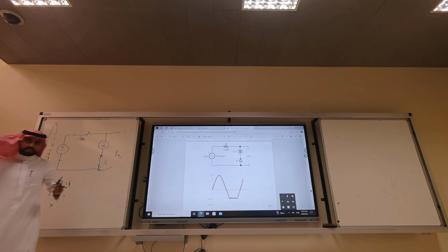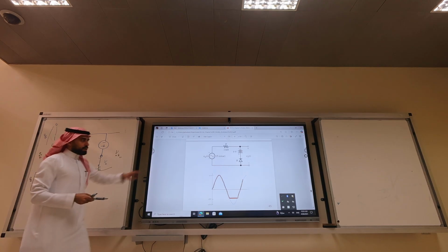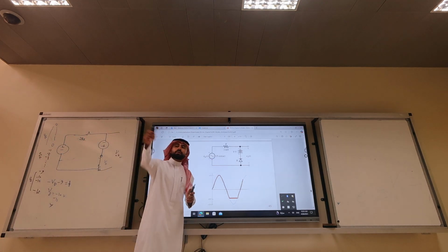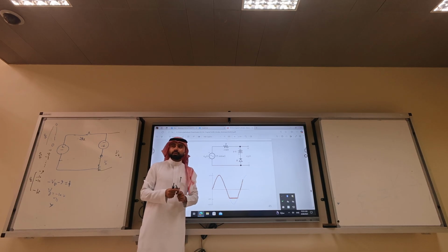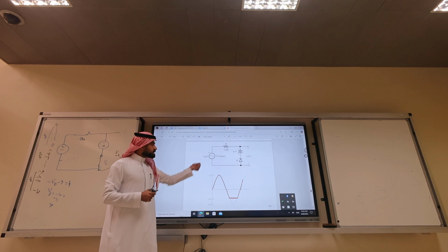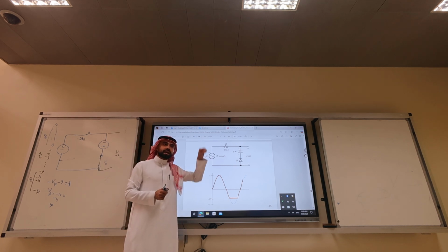That's how to analyze these circuits. The clipper circuit. Understand this example? We didn't do assumptions. Why? Because it's variable. So the best way to analyze circuits with AC sources and a diode is to study it case by case. Okay, Hatem?